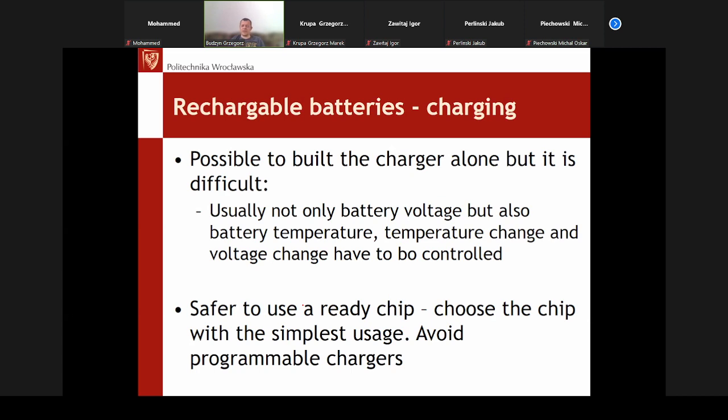In case of charging the batteries in the device, the advantage of such a built-in charger is that the case can be simpler. There's a lot of trouble making a cradle for the batteries, because the cradle has to be strong if it is to be opened by a user once a day or frequently. If we build everything into our device, no cradle is necessary, because there's no accessible cradle. We need to put the battery somewhere, but it can just be assembled and it's done.